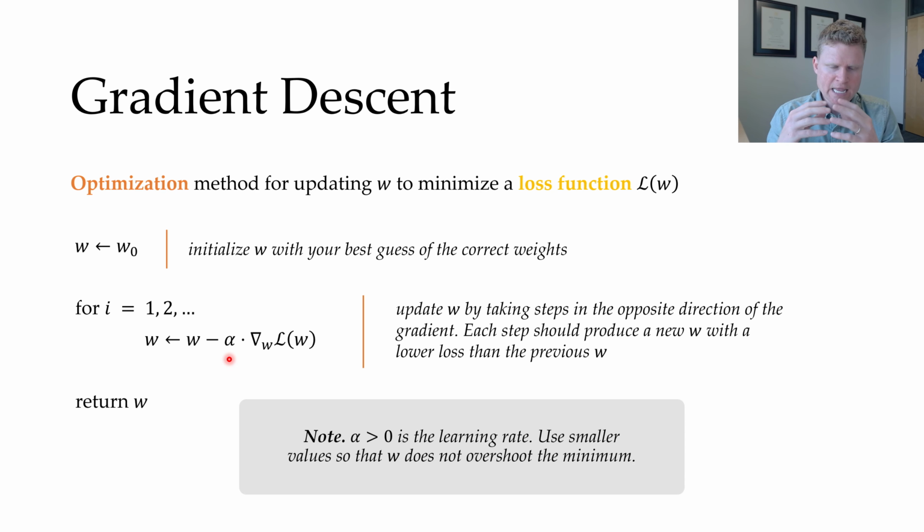So increasing alpha is going to cause you to have fewer steps, but you might overshoot your goal. And so it's actually better to start off with lower values of alpha so you can converge to the minimum here. Just like what we had for numerical inverse kinematics, we generally like to pick smaller values for alpha so we don't miss out on the optimal solution.